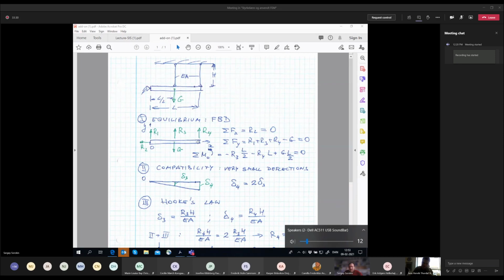So there are a lot of inconsistencies here, and I have to highlight them to be fair, but it's something which has been checked thousands and thousands of times. The first thing is that the equilibrium equations, these ones, are written in the framework of mechanics of the rigid body. So we sketch this free body diagram. We ignore deflections. We just say that this bar is absolutely dead horizontal. And then we write these equations.